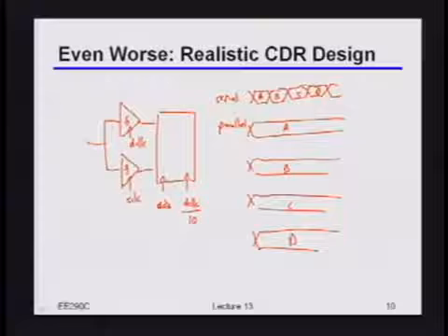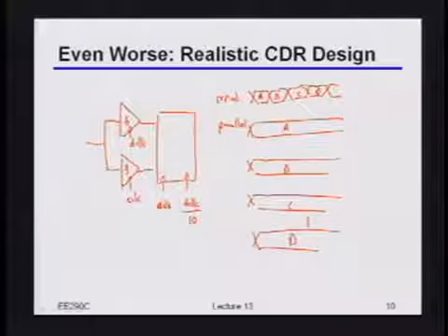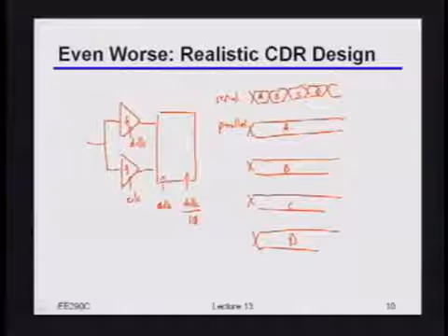So typically then what will happen is you'll take all of those parallel things, and rather than do all the same computations you would have before, you'll just look for some aggregate behavior. So let's say I do a divide by 10. I may have had 10 possible up and down signals, right? So I may say, only if I get more ups than I do downs across that whole window, only then will I actually move up, right? Or maybe only if I got 2 more ups than I got downs, only then will I move up, right? And so on and so forth.